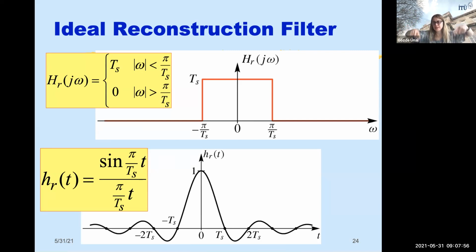So it's really not the same sine repeating itself, not periodic, but it's really a decaying sine. And it's an infinite extent signal, right? Is this filter realizable? It's an infinite time signal. It's an ideal signal, or ideal filter. It's what we call an ideal low-pass filter, remember? And for the sampling problem, it's an ideal reconstruction filter also. Why ideal? Because with this filter in place, we can perfectly reconstruct the signal back. Are there any questions until here? Do you guys see what I'm talking about at this point?